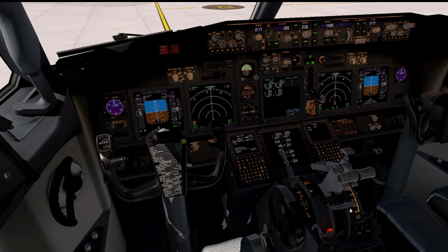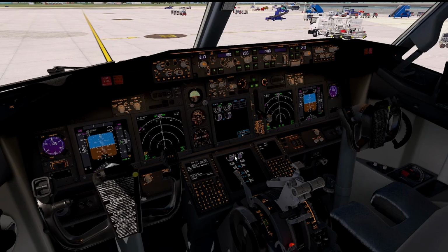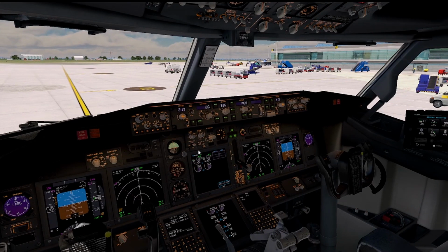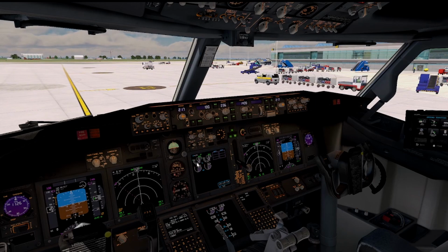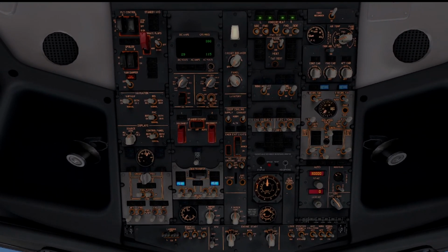Give me just a moment. So we did the exact same thing on engine number 1. We flicked this to ground and we introduced fuel when the N2 is at 25%. When you have done that, you have around 19.5 on your N1 on both engines. Your engines are then stable. What you then want to do is put your engine start switches to continuous and continuous.